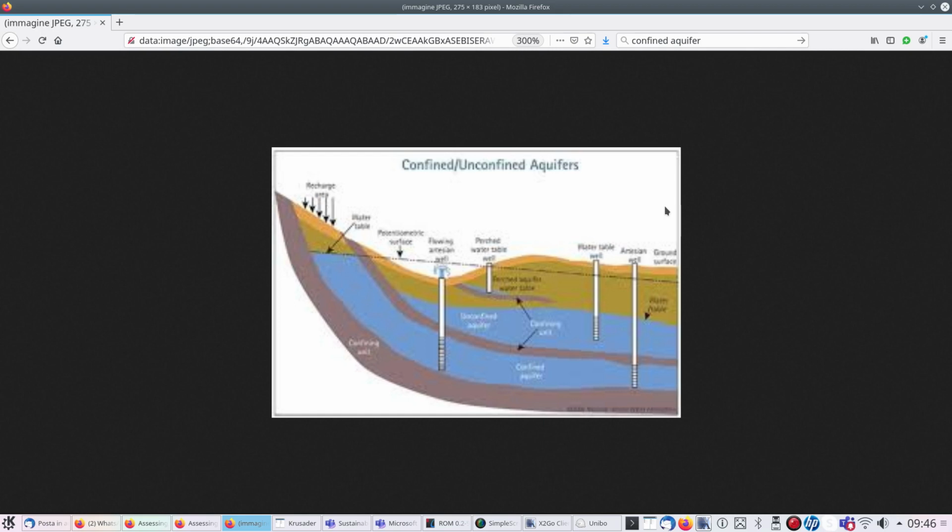Infiltration in permeable soil, in the permeable part between the two impermeable layers, that is emerging upstream. So you have the permeable layer where the lower aquifer is stored, that is emerging in the uplands on the left, and from there it can get water from infiltration. And then water goes down, gets trapped into the confined aquifer.